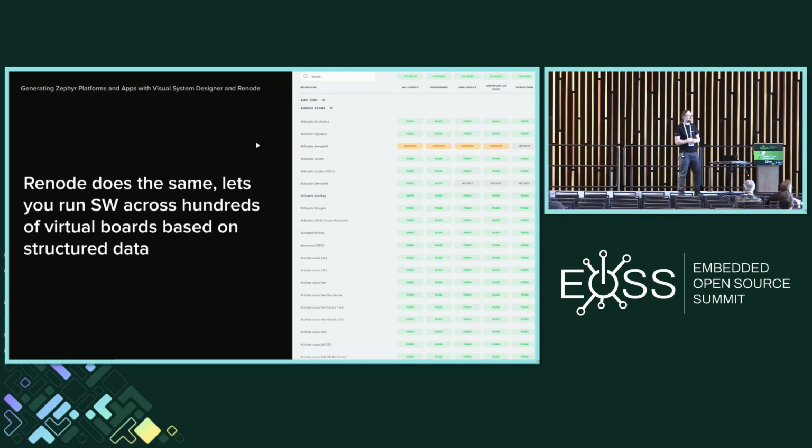Having said this, there's a lot of great stuff that comes to your rescue. And it's the same as in Zephyr. You have a driver that might be addressing a certain peripheral. If that certain peripheral is present in a number of different boards that are related, what Zephyr does is it takes configuration, it addresses this via device trees, and you just instantiate the same driver, perhaps on a different address, perhaps with some configuration options. But generally speaking, you reuse code all across the board in a very strict and efficient and configurable manner, so that you don't duplicate code all the time.